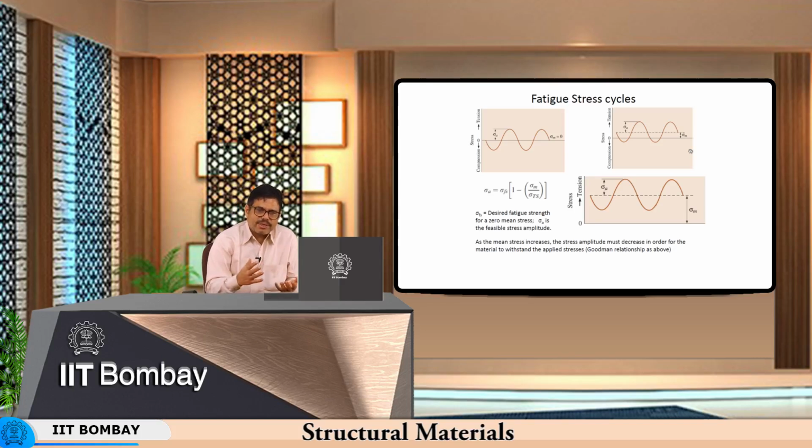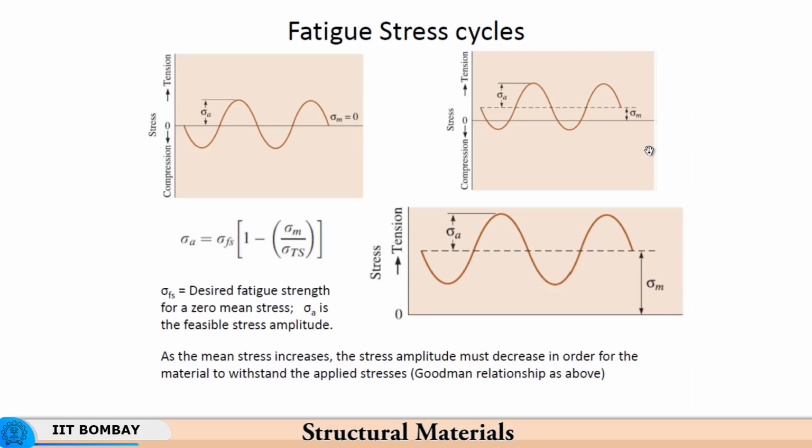The only thing is the tension is fluctuating, that is about it, but the tension remains at all times. So, there is minimum tension, maximum tension, and there is a mean tension being experienced by the material. So, what we find is that in this fatigue loading, there is no occasion for the material to get into a compressive regime.